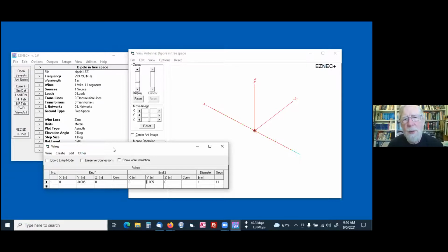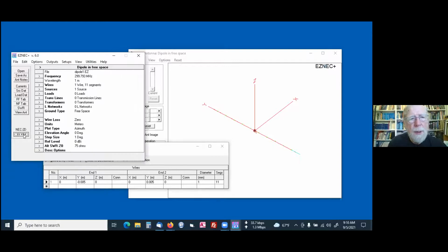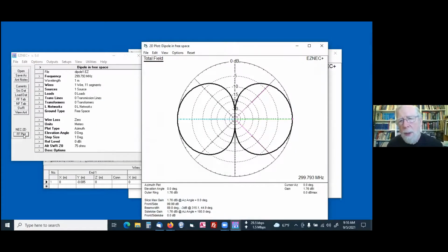I really should have some graphics to illustrate that, but I don't. So I'm saying that if an antenna is 100% efficient, no loss, then the smallest possible gain it could have is 0 dBi, and that would be a perfectly circular pattern in all directions. So let's see what kind of gain and pattern this thing has. Okay, looks pretty much like the half wavelength dipole, doesn't it?